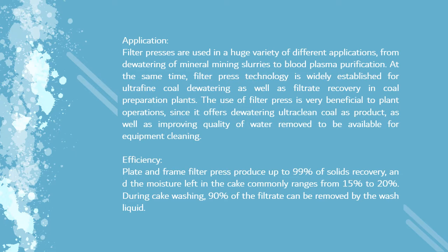Efficiency. Plate and frame filter presses produce up to 99% of solid recovery, and the moisture left in the cake commonly ranges from 15% to 20%. During cake washing, 90% of the filtrate can be removed by the wash liquid.